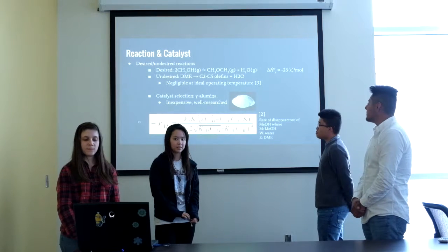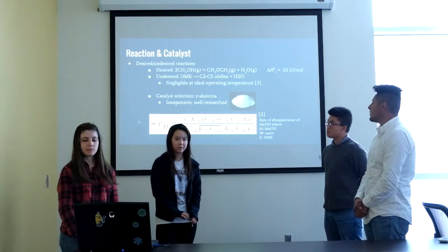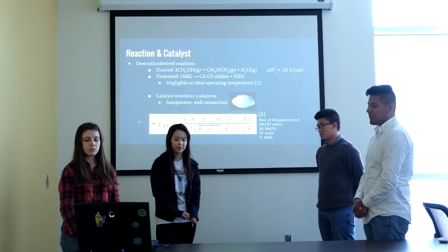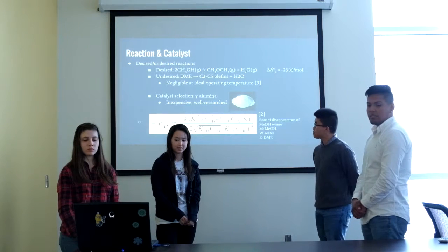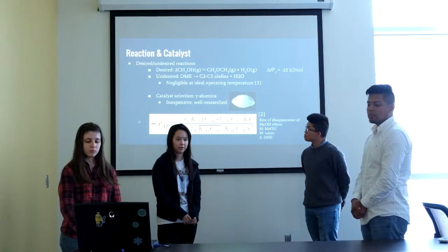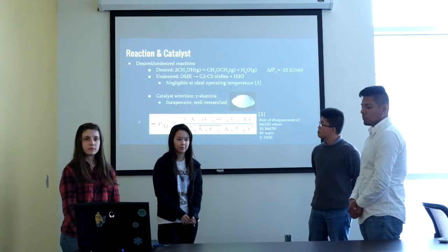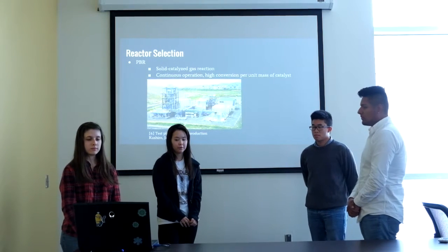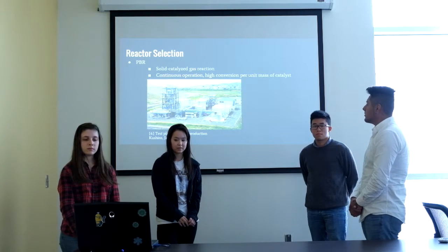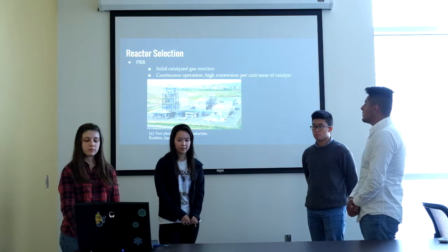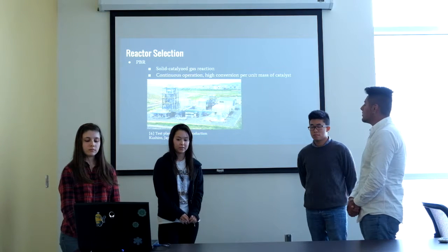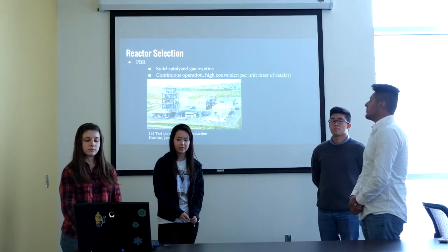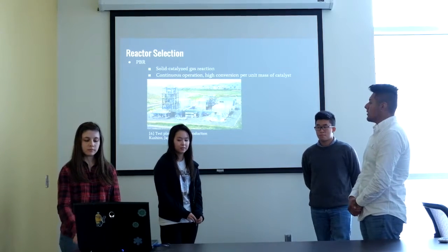For our rate law, this was taken from a research paper. The linear Hinshelwood mechanism is actually pretty frequently associated with this reaction. However, our rate law is not based on that because this rate law was found to be more realistic in terms of representing the kinetics of our reaction. And for our reactor selection, we chose a packed bed reactor. They are most frequently used for solid catalyzed gas reactions such as ours. They also have the advantage of being continuous operation and having a high conversion per unit mass of catalyst.